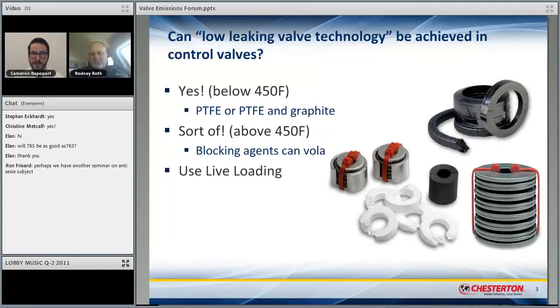All right. So if I'm an end user and I want a low emissions control valve, I'm going to be looking for probably that ISO 15848 testing. Correct. If you guys want to know anything more about that, you can see the recording of my last webcast with our test engineers, where we discussed in depth more of these API 622, 624, ISO 15848, and the German TA Luft standards, which are the most widely used and accepted low emissions valve and valve packing test standards.